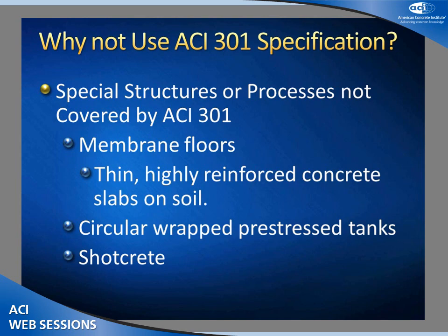We also cover Shotcrete. 318 and 301 don't currently. Well, 301 doesn't currently cover Shotcrete. 318 doesn't cover it directly, though I have talked to 318, and they admit that Shotcrete is something that can be used for 318 structures. But we actually have specification requirements for Shotcrete in our new document.